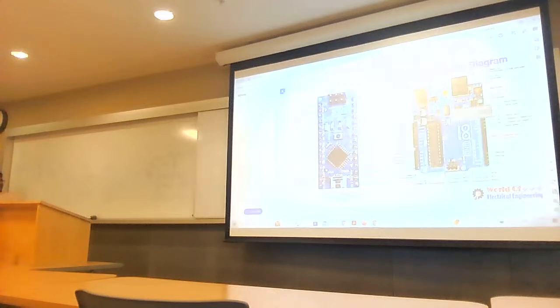If somehow it makes 2 gigahertz, then the up signal is manipulated so that it increases the frequency. And let's say it goes from 2.8 to 3 gigahertz, we need to bring the frequency down. Then it will generate a down signal that makes the frequency go down a little bit. So this is the job of a charge pump. Depending on this, it will produce some current from up or down.